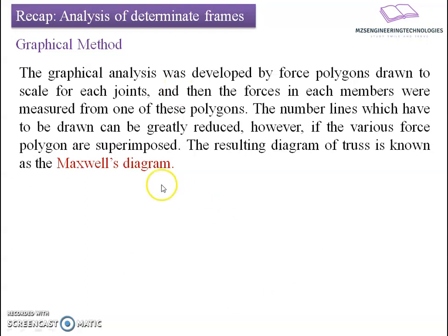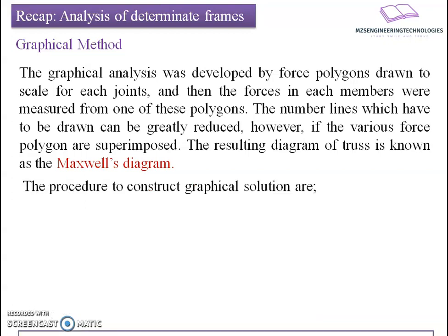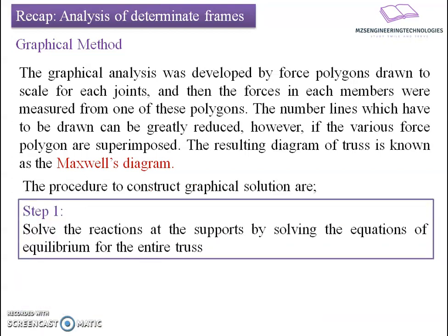Okay, I will not go in depth into how to construct the space diagram, how to construct the vector diagram, how to scale up these things. Just a review, I am going to put these things in front of you. I will put here the steps for how to construct the solution with the help of the graphical method. The procedure involves the following steps. Number one, we are supposed to find out the reactive forces by applying available static equilibrium equations.